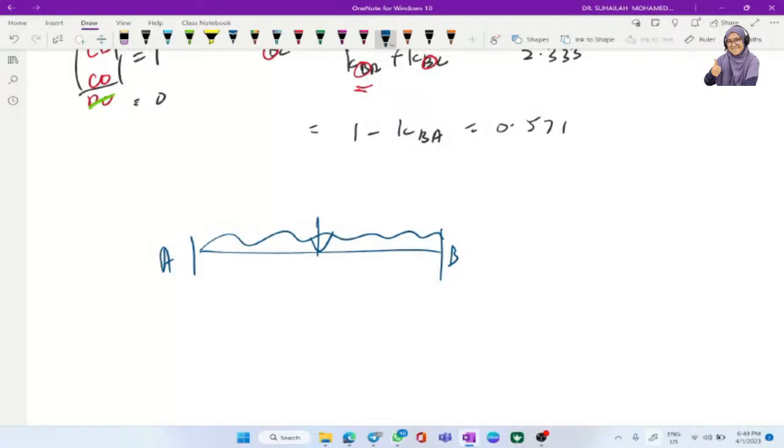The beam will bend, and due to the loading at both fixed ends, there will be moments that push the beam back to its original position. We call these counter forces the fixed end reactions, and this is the fixed end moment.